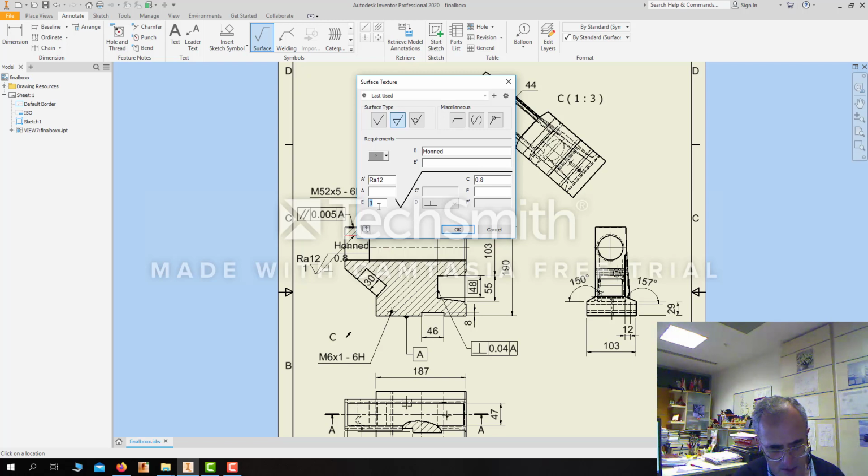Well, in this example, say that 0.5 millimeters is the allowance. At the beginning, the diameter of the hole is 0.5 plus 0.5, 1 millimeter smaller. After the cutting process, it is going to be in the final size, 1 millimeter greater.